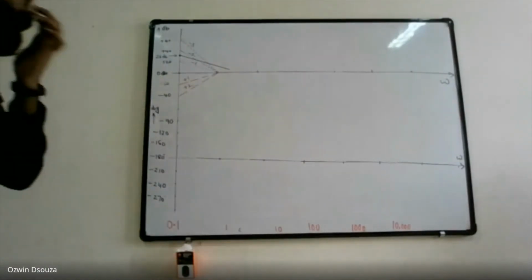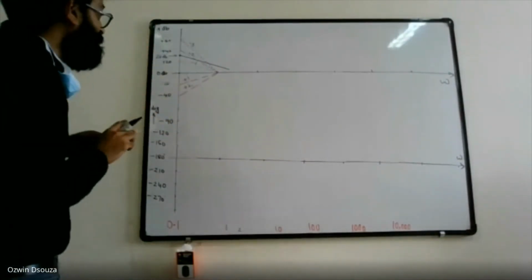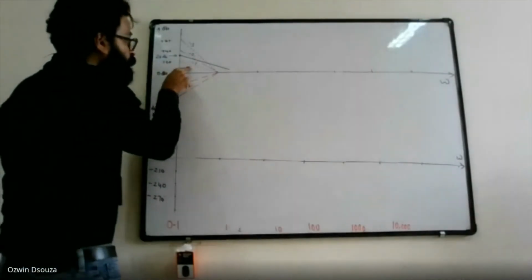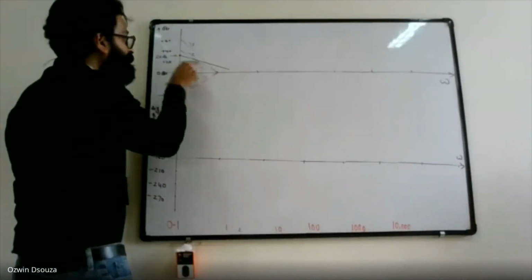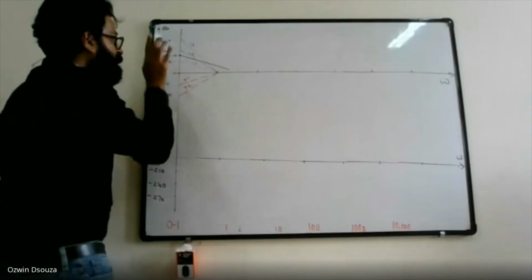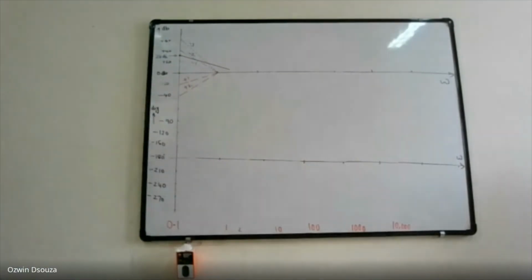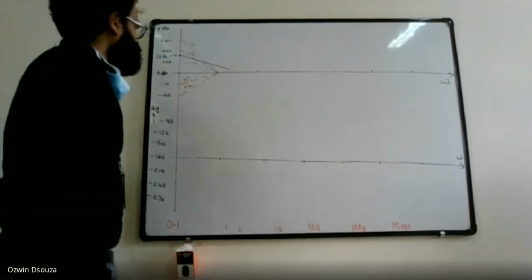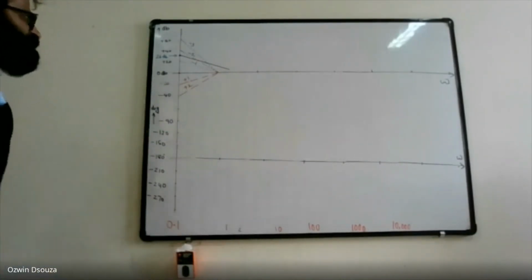Now, if you have drawn properly, the minus 1 line will be parallel to the line which you have drawn from 26 dB, right? That is the reason we draw the reference slope lines. Reference slope lines will help us in drawing the magnitude plot. That is one trick.